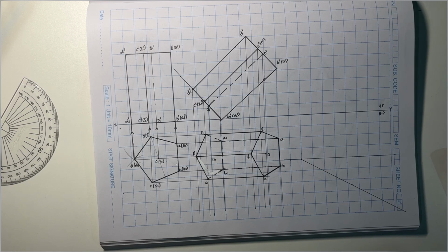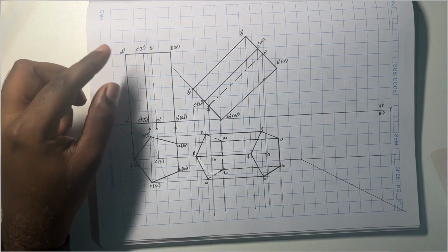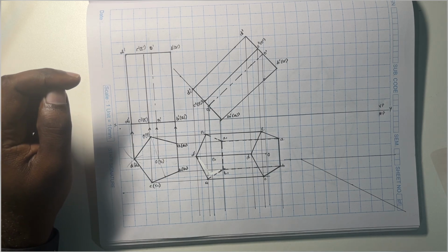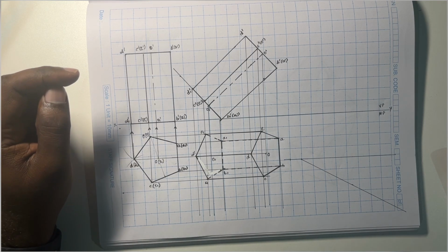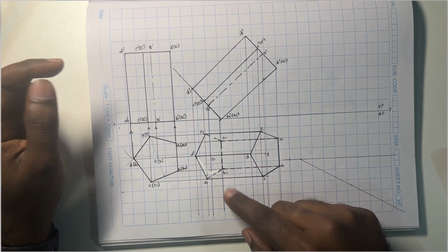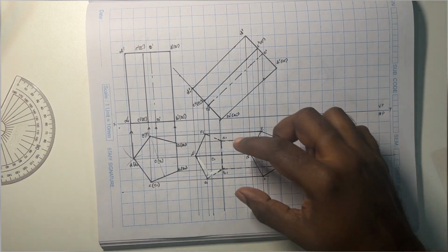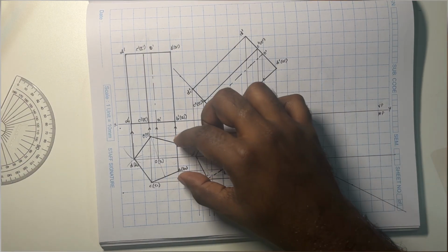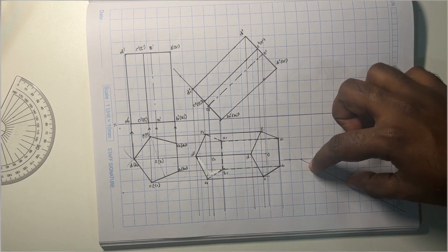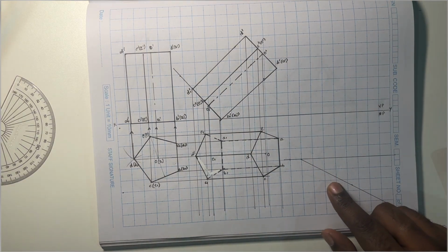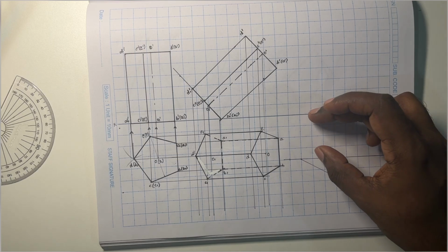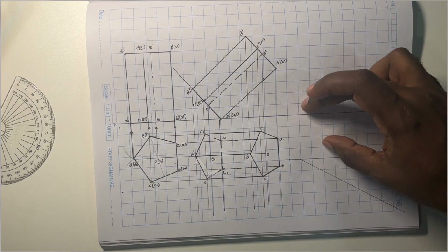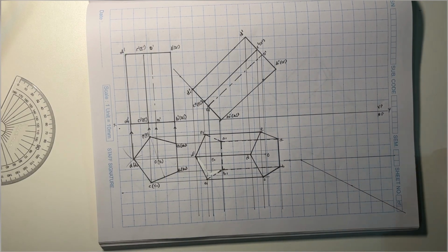So now we need to continue with placing the prism on the 30-degree line, that is, the edge on which it is resting should be placed on the 30-degree line. So A1, B1 is the resting edge, and now we need to consider rotating the prism in such a way that this edge A1, B1 on which it is resting initially is on this 30-degree line. So I've drawn a 30-degree line here. I've taken a considerable distance from the XY line so that this prism will not go above the XY line when I'm doing the rotation.